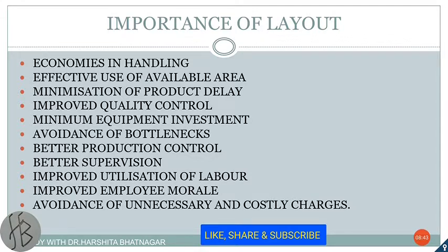There are different importances of layout. First, economies in handling. I told you if the layout is good, then material handling will be less, then material cost will be less, and damage to the material will also be less. Effective use of available area: every foot of space should be utilized properly. Minimization of product delay: if the layout is good, then the product delay will be minimized. Improved quality control. Better supervision will be there. Minimum equipment investment: if the layout is proper, then you need to invest little or minimum in the equipment.